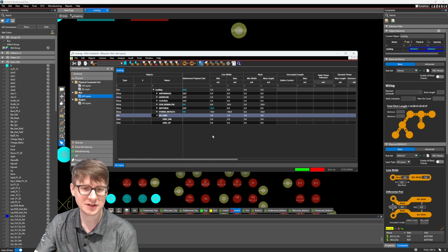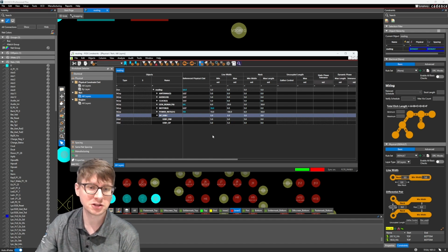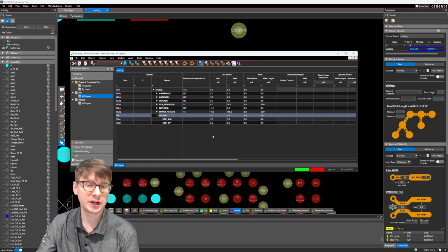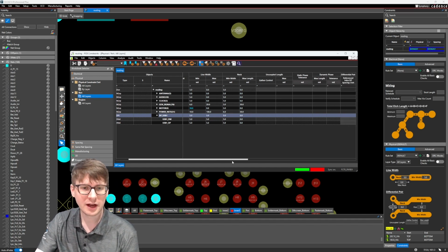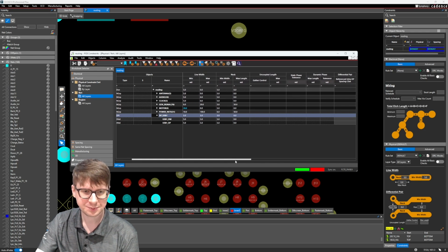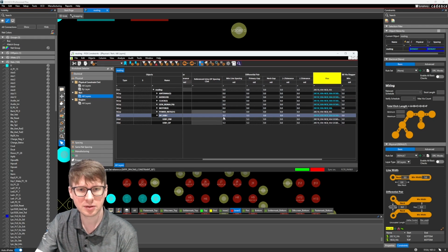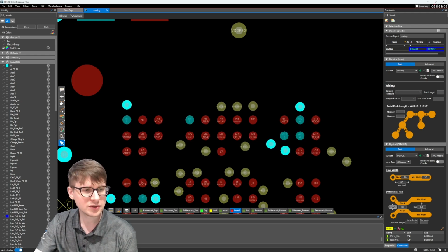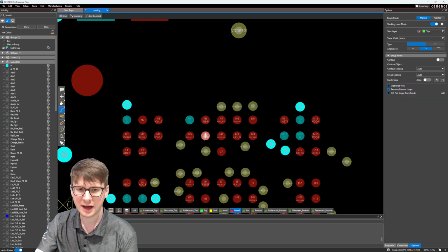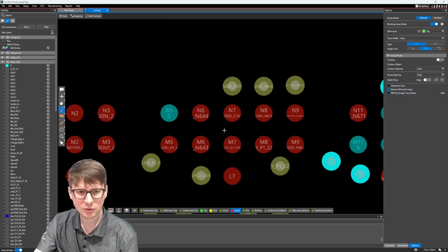And then based on the line width and the distance to the dielectric below and the dielectric constant of the material that you're referencing, or that is used as the return path, you will then have an impedance. But you can set your line width in Constraint Manager. If you have a differential pair, you can set your minimum line spacing, your primary gap, your neck gap, and the tolerance.